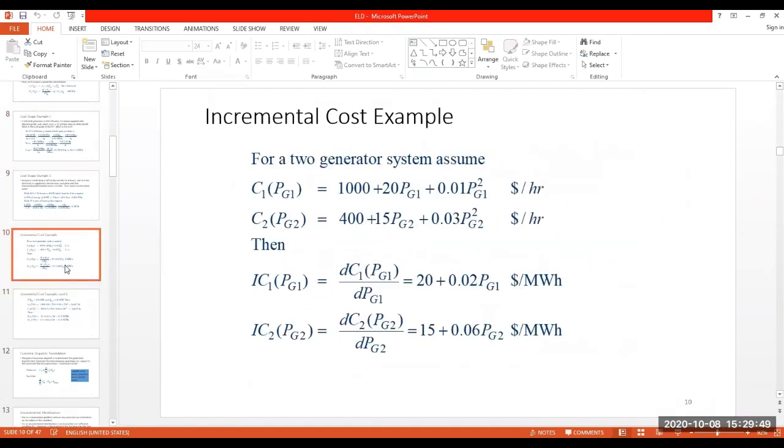So what I'm saying is basically, we considered only these cost functions, right? Fuel cost functions for, let's say, our thermal power plants. Along with these, can we introduce some other constraints or some other sort of costs associated with our emission? Could the emission be expressed in terms of generation, like we represented the fuel cost in terms of generation? There are ways, and that is covered in minimum emission dispatch.